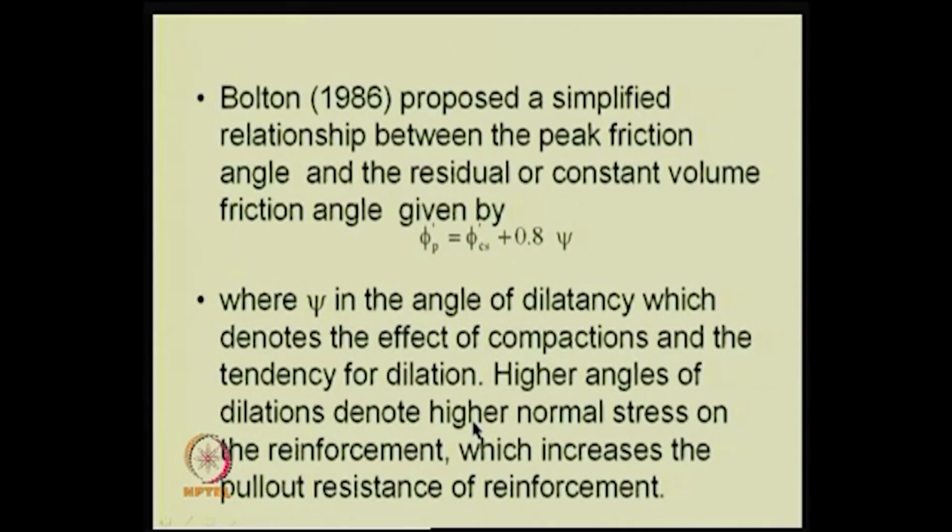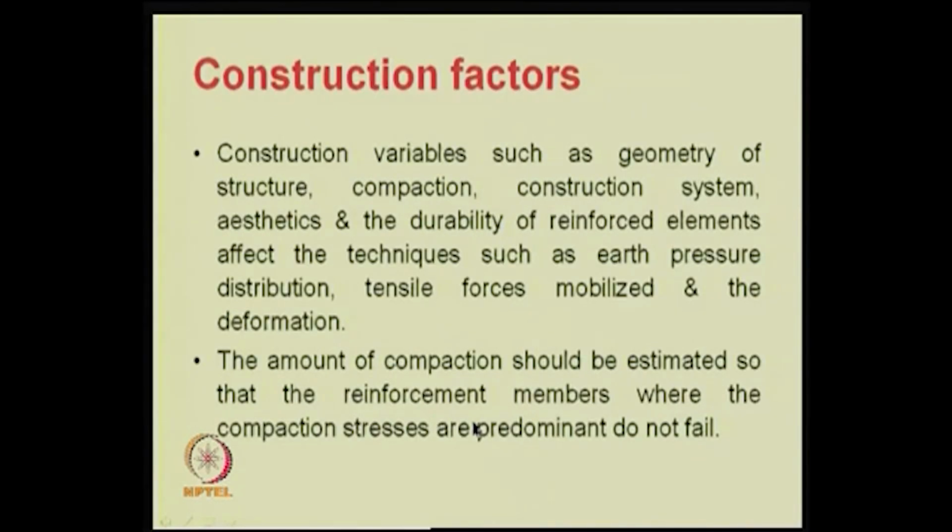Actually, what happens is that pulling out when there is good dilation is not easy, because compaction induces a dilation tendency. But then the soil can't dilate, and in that process it holds the reinforcement much stronger, because the effective stress is more now.